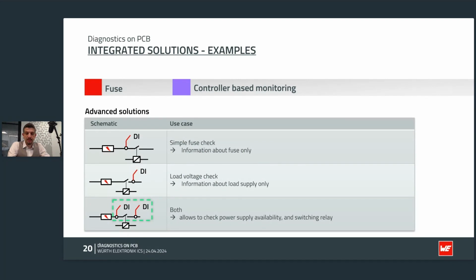If, for example, the relay is not switched on through the controller's output, the relay could be defective. In the same manner, if, when turned off, the input after the relay is not losing its potential, the relay could be stuck. Going one step further, if the input after the relay gets powered, we could even detect a short to bat on the wiring harness to prevent the output to be activated at all.